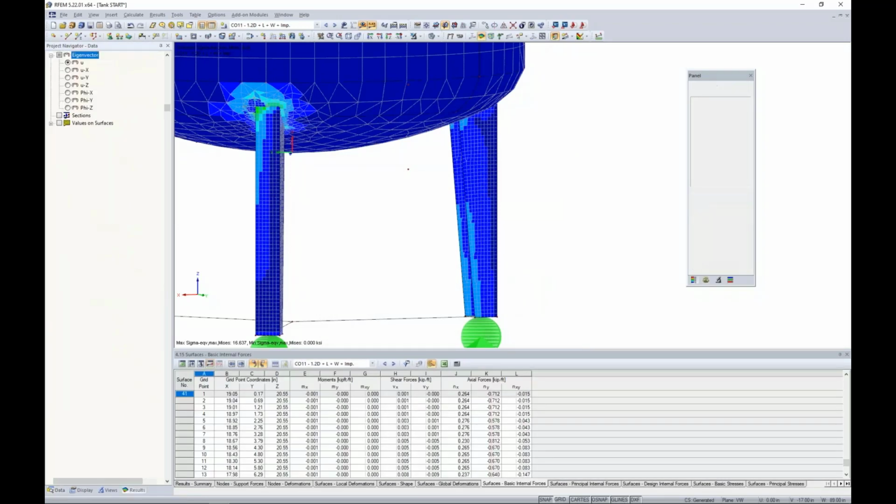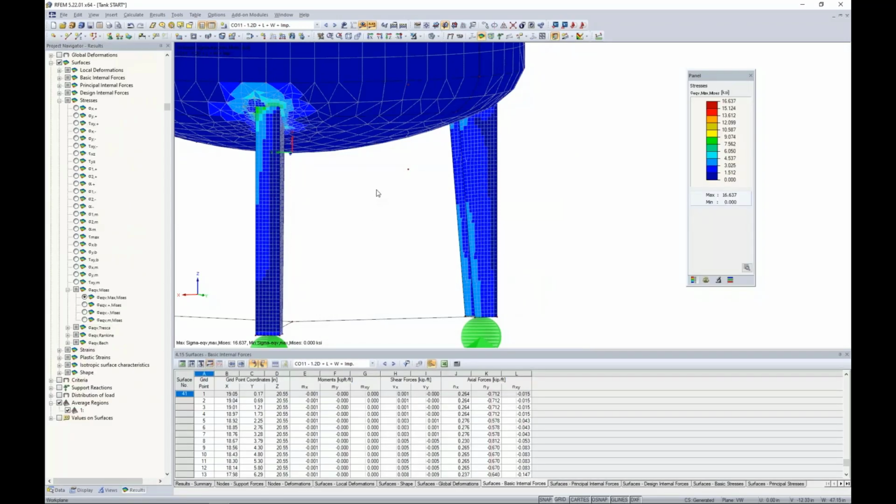So I went ahead and ran this. I'm reviewing our stresses on the structure just like what we've seen before. And in reality, I'm looking at my von Mises stresses. There really isn't much difference here with my leg on the right hand side. But I also didn't really scale that imperfection up too high, only 0.014. So I think it can be concluded that it really doesn't have much impact on the stresses at this location, which isn't necessarily a bad thing. Maybe if we had a thinner material here for our leg elements, we would see more of the results.